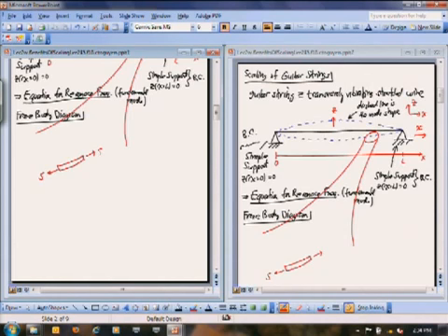One of the forces that I have is an inertial force. The fact that this beam is moving means it's got an inertia. An inertial force is equal to, from your physics courses, mass times acceleration. So I need to get an equation for mass, and I need to get an equation for acceleration here. Let me take this as a direction for my inertial force. And I can write down an expression for inertial force as m prime, which is a mass per unit length.